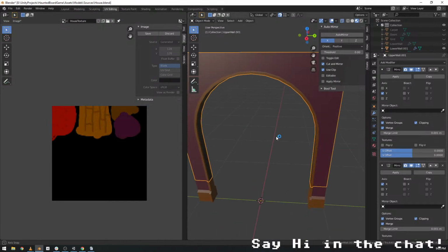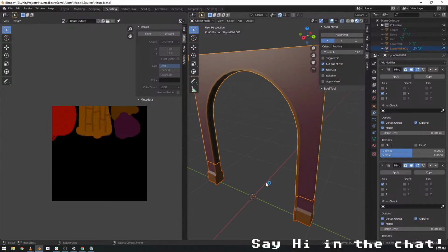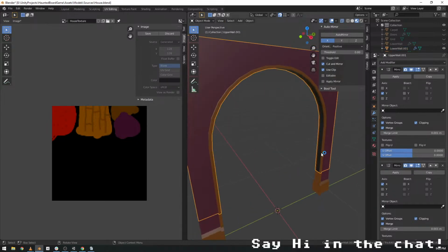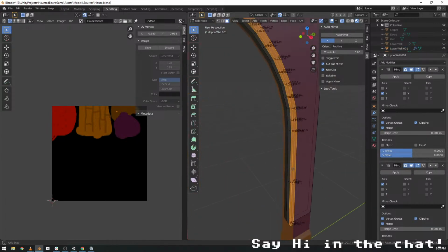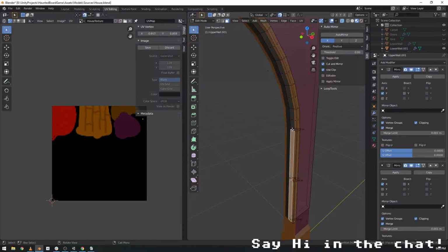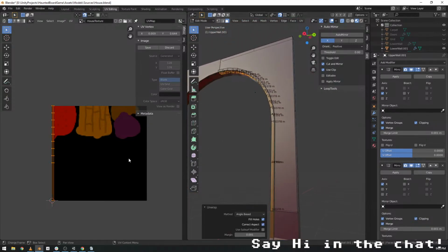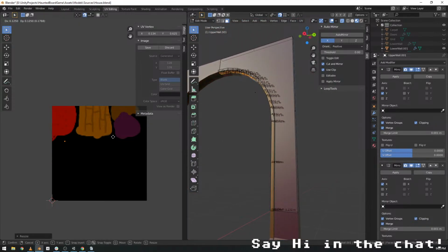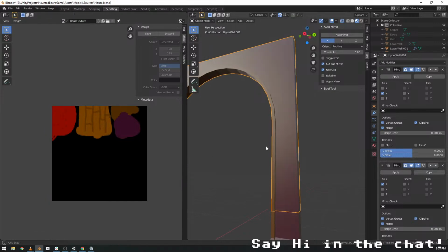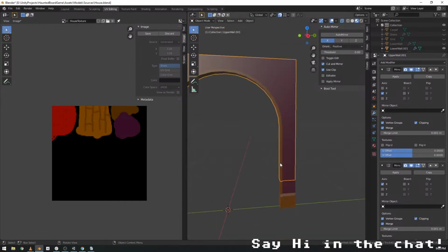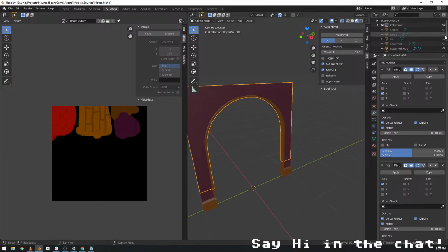Drop them on the frame. And again, missed one. Alt left click selects the band. Yep. Just re-unwrap them, scale them to 0, drop them on the brown. There we go. A nice doorway with some doors.